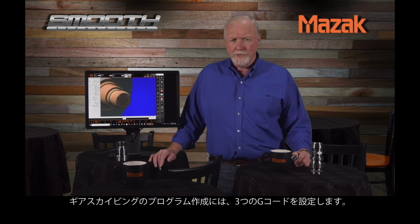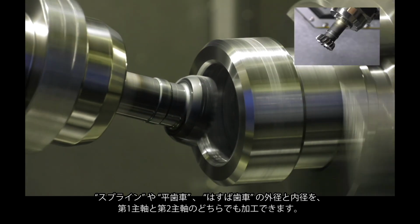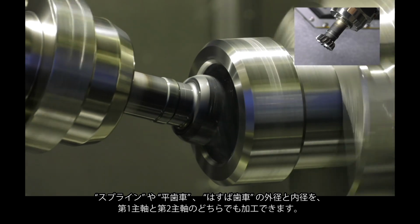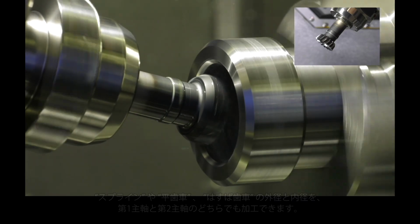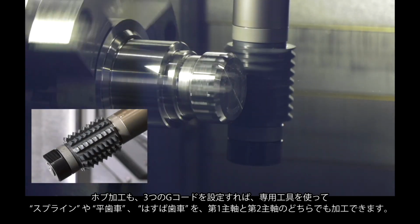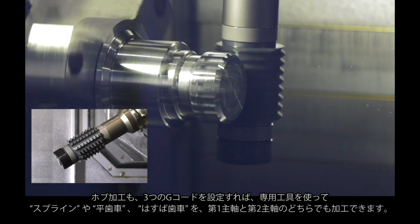G320 to 322 are for gear skiving with a spindle-mounted skiving tool. Skiving can form splines internally or externally. Both spur and helical gears can be formed on either head 1 or head 2 of a horizontal AG machine. G310 to 312 are for gear hobbing with a spindle-mounted hobbing tool. Hobbing can create both spur and helical gears and can be done on either head 1 or head 2.